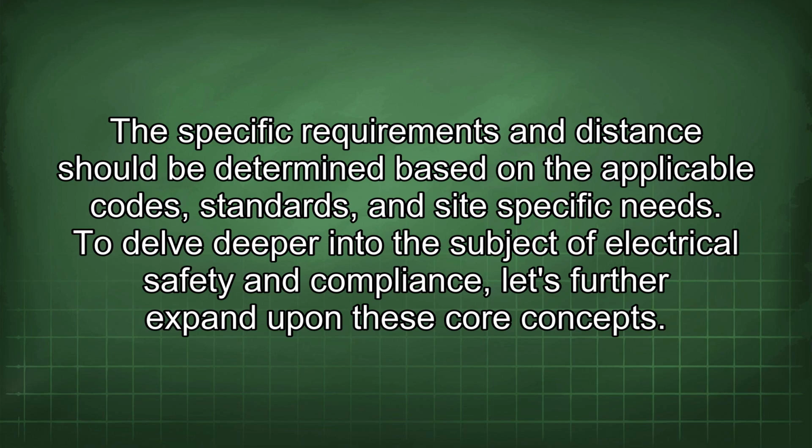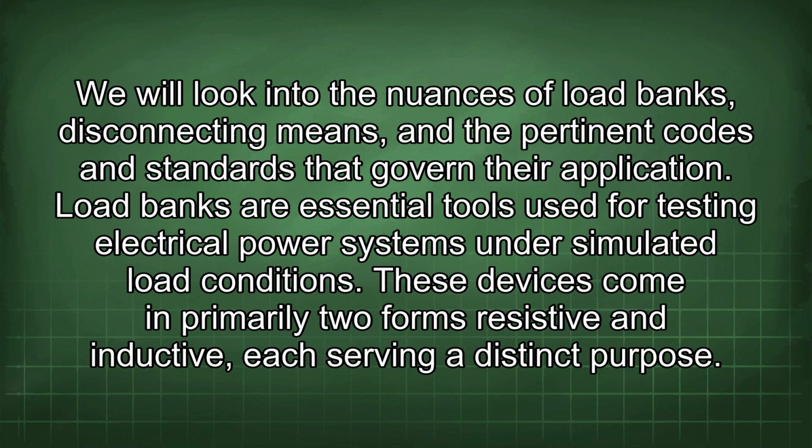To delve deeper into the subject of electrical safety and compliance, let's further expand upon these core concepts. We will look into the nuances of load banks, disconnecting means, and the pertinent codes and standards that govern their application. Load banks are essential tools used for testing electrical power systems under simulated load conditions. These devices come in primarily two forms: resistive and inductive, each serving a distinct purpose.